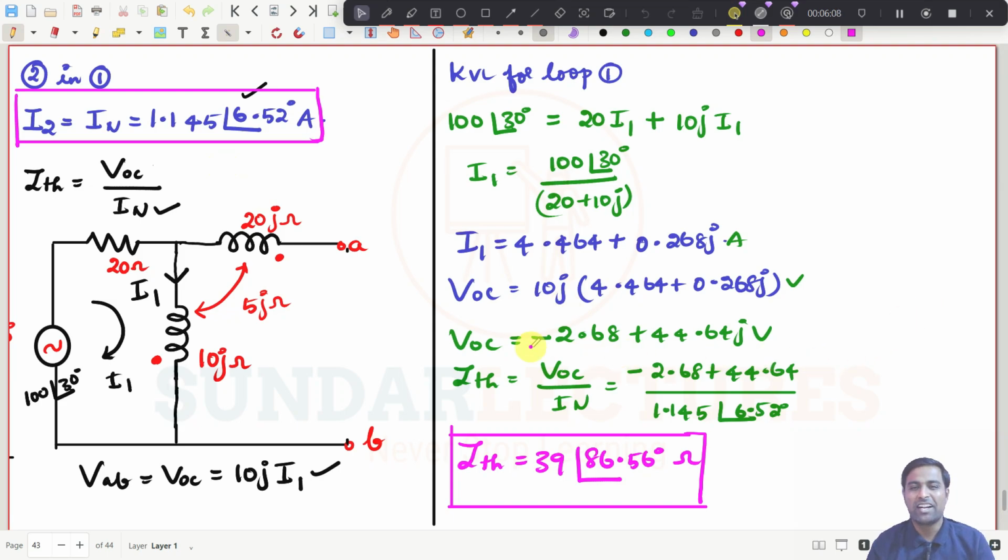See here, for every problem, it is easy to find the Norton's equivalent circuit. Even if you go for superposition or Thevenin's theorem, whatever it may be, you will get the answers, right? So we are just applying electrical circuit theorems here in coupled coils. That is the beauty of studying the steady state analysis of mutually coupled coils.